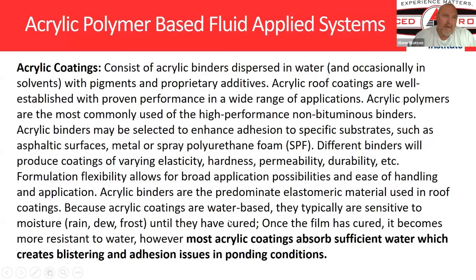And unlike PMMAs, after a product's been down for longer than 24 hours, there has to be a chemical reaction again. So you have to wipe it down with their solvent in order to activate it, so that the cross-link process by which it chemically bonds to itself is stimulated. You can't just apply the mixed product over your existing layer without having done that primer or that wipe down with the solvent, or you will get poor cohesion. So understanding that concept's key as well.